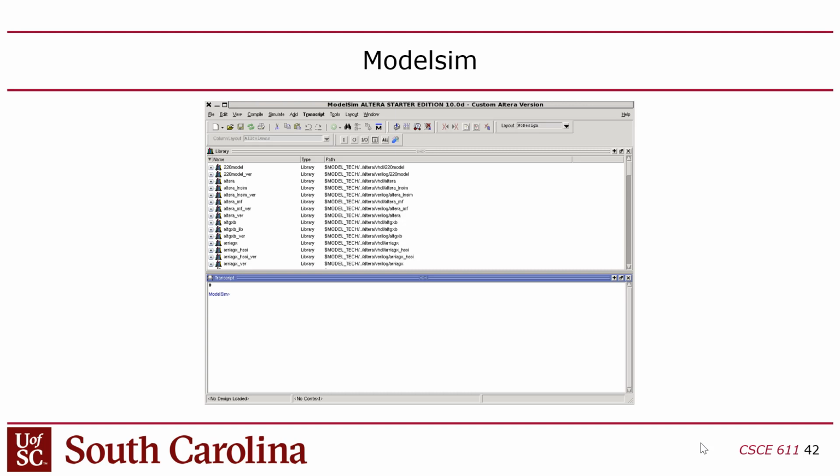Okay. Now you can compile in here too. So there's a GUI. You'll notice that there is a compile menu here. So you can compile designs through the GUI, or you can compile them through this little command line interface, or you can compile them in a shell. I usually just compile them in a shell. I type vlog space star.sv, and that just compiles all my SystemVerilog files in the directory. And it puts them in the work directory. The work directory will then pop up as a work library, assuming, of course, that you launch ModelSim from the same directory that you compiled the files in, right?